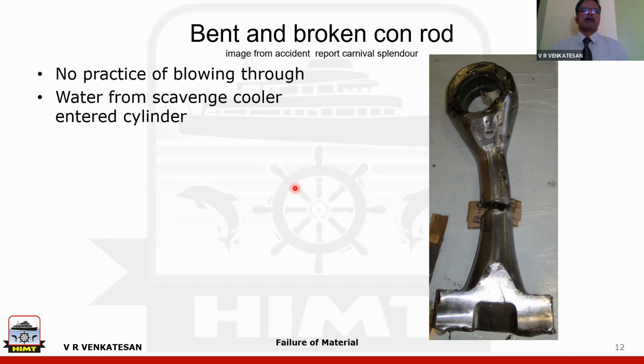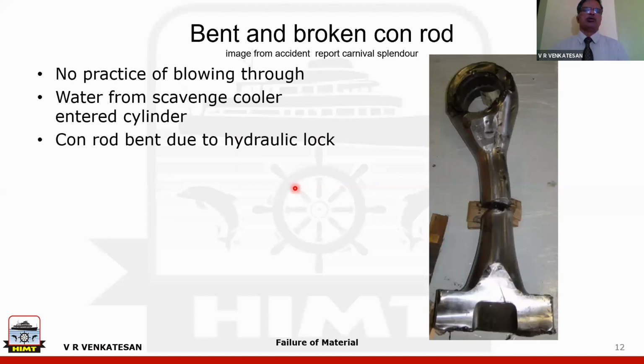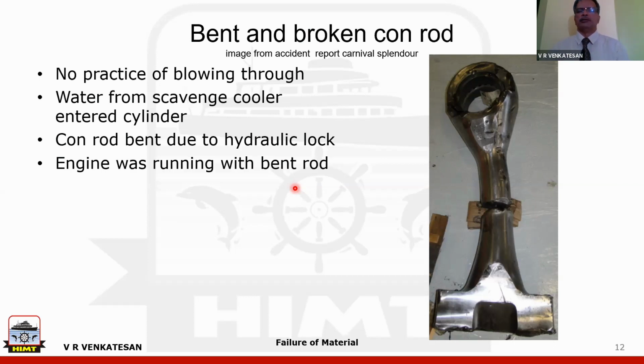Water from the scavenger cooler entered the cylinder because of a leakage. That scavenger cooler developed leakage and water entered inside. And due to this water ingress, when the engine was started, the connecting rod bent due to hydraulic lock. Now, even though the connecting rod bent, the engine was still running.